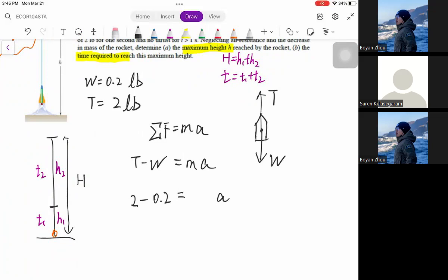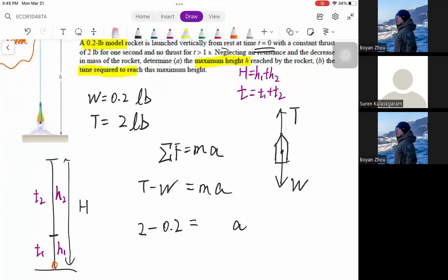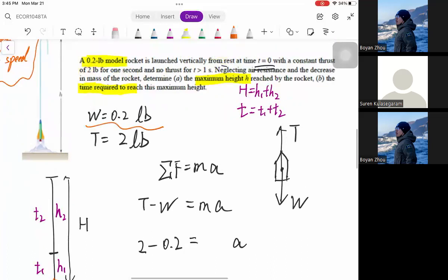The mass here, we need to calculate from the weight. When we have a question in SI units, usually the weight is given in kilograms or grams, which is a mass unit. But in empirical units questions, the weight is always given as a force. So we need to calculate the actual mass from the force.